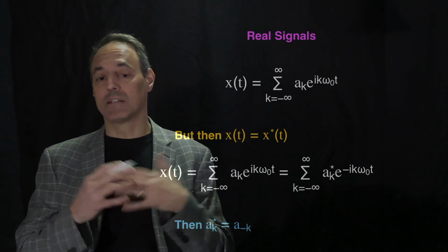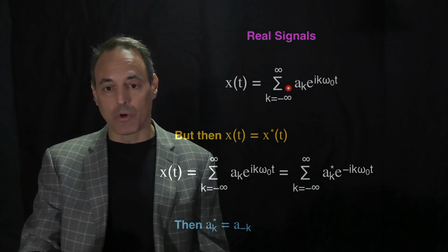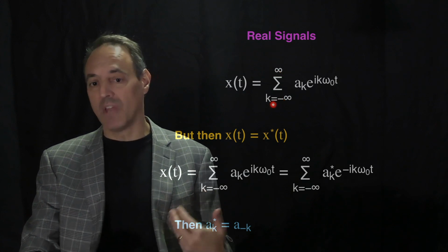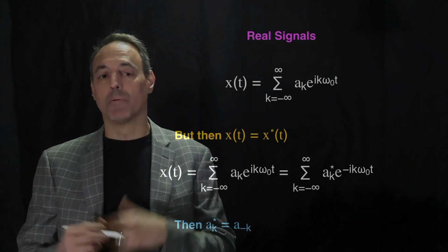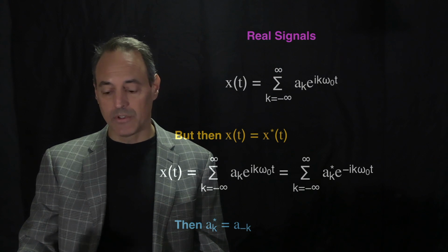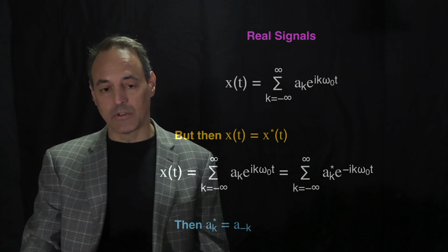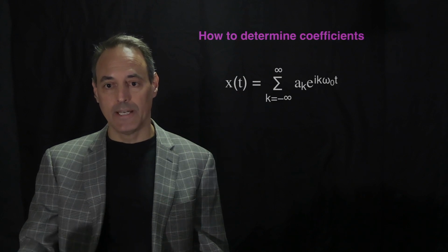Because what you'll get is sines and cosines directly, because the negative part will contribute with the positive. So if k equals -3, it will contribute with k equals 3 because of this relationship to produce, let's say, a sine or a cosine. So that's a nice feature, and you can always guarantee signals are real if you have this property here. Okay?